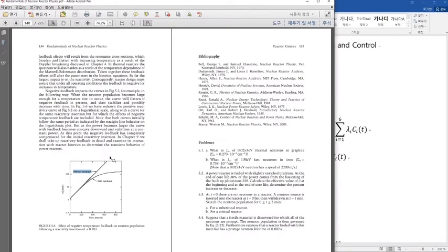In the opposite case, when we provide negative reactivity, less power will be generated. That means that the temperature of the fuel and coolant will decrease if sufficient power was generated in a steady state condition. Then their temperature will gradually decrease, and this decreased temperature will have the effect of increasing the power.